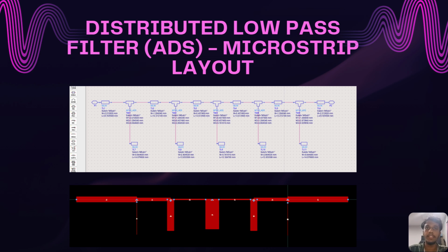As you can see clearly, all the vertical traces are open at one end. This perfectly visualizes why we performed those complex Kuroda identity calculations earlier. It allowed us to convert an unbuildable circuit into an easily manufacturable board without needing to drill.